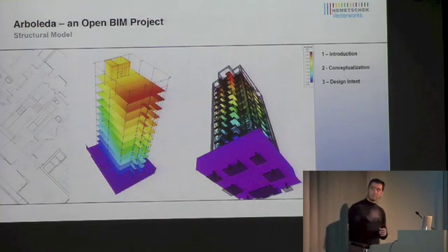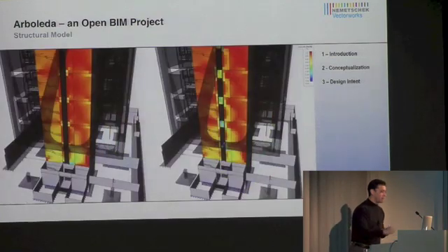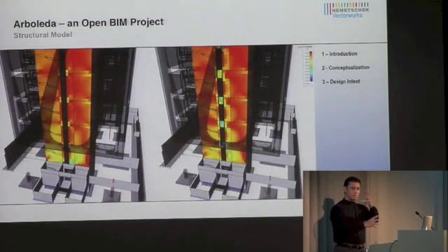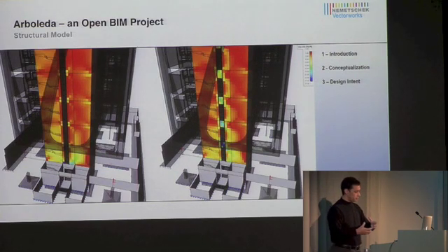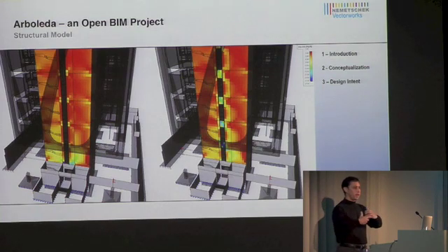This is what happened by February, end of February. Now, because of that movement of the building, he said, listen, Luis, your building requires a little more, it's too flexible. So the core of the building, your concrete walls require coupling because it's just swaying too much.